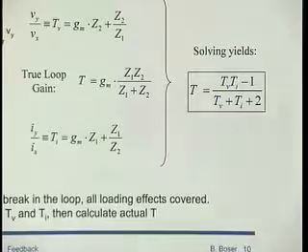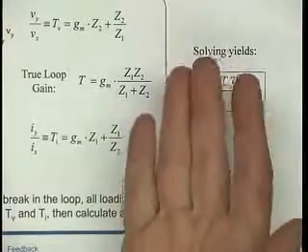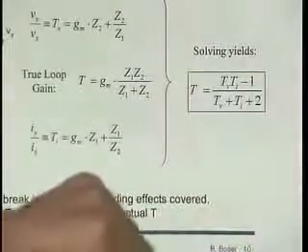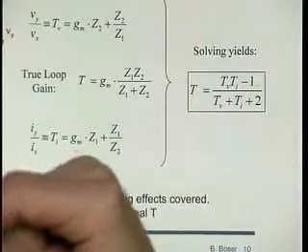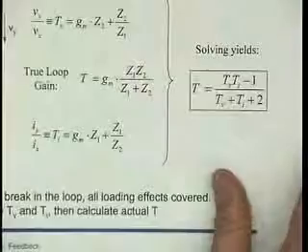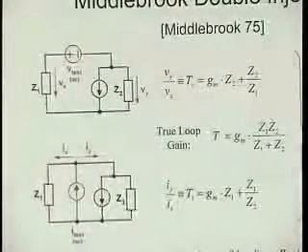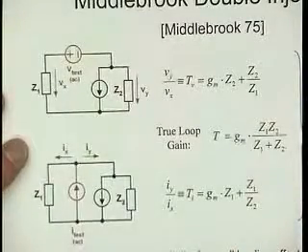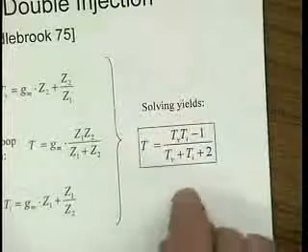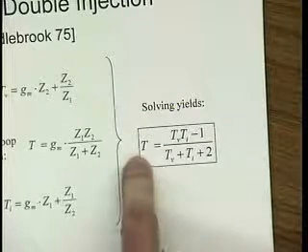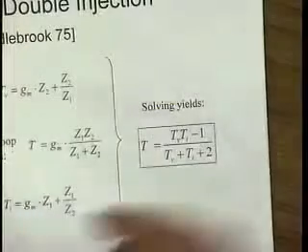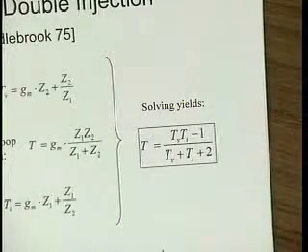Those gains are not necessarily unitless, but the loop gain better be unitless, because if we break the loop at some point, out comes a voltage, and we stick in a voltage on the other side again, or likewise for current. In practice, that's what we're going to do when we analyze the stability of a circuit with SPICE. We're going to run two analyses, and then using this equation, we combine the results of these two analyses and plot a Bode plot of T of S, and then we use something like phase margin as our stability criteria.